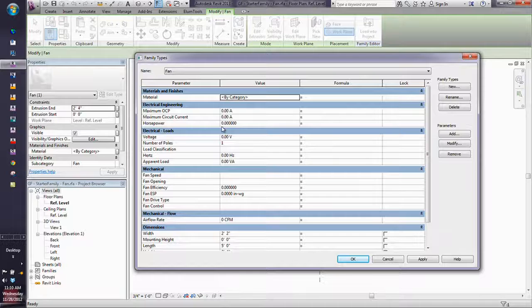What controls a shared parameter when you put it in the file? How do you know that it's unique to that object? It's the what? The GUID. It's not the name. So by having our standard shared parameters in these starter families already, I don't have to worry about somebody loading up something in a project that doesn't match the schedules that we already have defined.